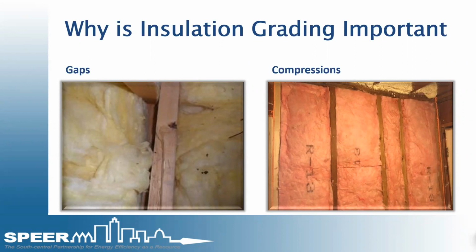A higher percentage of these basically lowers the effective R value throughout the building envelope. It's kind of like a domino effect. So a poor job of sealing the air holes in the air barrier, having a poor job of installing the insulation, or you've got a lot of compressions. Then you add windows and doors, and you basically cut holes in the envelope. And then you kind of lose the whole value of why you're insulating that wall to begin with.